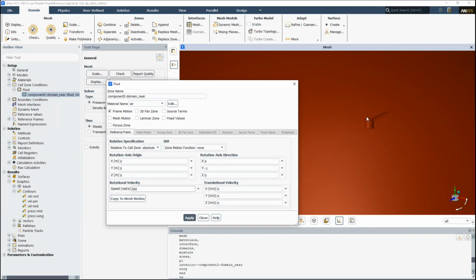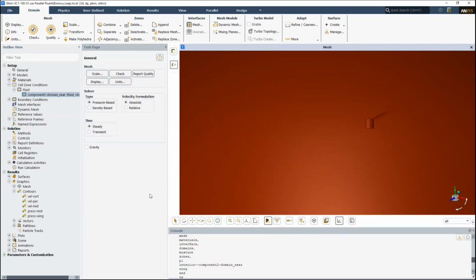When we have something that doesn't have a cyclic nature, or is moving in more complex ways, then we can do things like turn mesh motion on, okay? And that will be a transient analysis. So you'll need to capture that time step by time step because there's no constant nature to the way that object is moving. Does that make sense? Thank you. Cool.